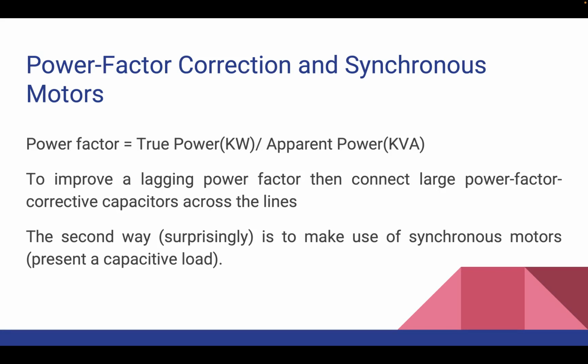Synchronous motors are installed specifically for power factor correction purposes, and when they are used this way, they are called synchronous condensers. These motors do not drive a load. Instead, they operate to spin and provide just capacitive reactive power to improve the overall power factor of the system.